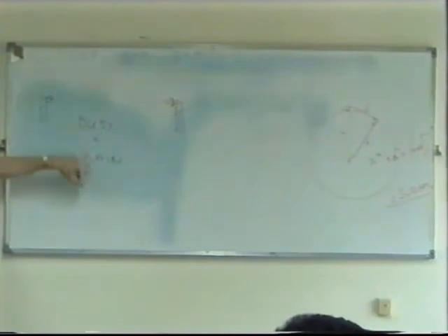This is probably less common, but it does indeed, yes. Particularly rain, more so than dust, in fact. It's all to do with the physical size of the particles that are going to exist between your transmitter and receiver. The size of those particles that are going to affect your communication depends on the wavelength.